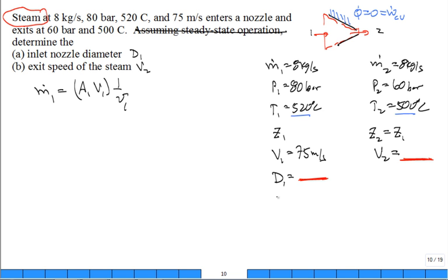Okay, go back over here now. I need to get the specific volume at state 1. I probably, maybe, needed it at 2 as well. Maybe I need the internal energy at 1. Maybe I need the enthalpy at 1. Once you get to the property tables, when in doubt, grab them all for that state. These two, pressure and temperature, fix the state, and we can look up in the steam table and get values of v1. What is the value of v1 for this problem?